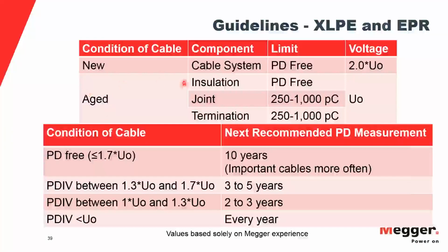You have to consider that the insulation material is constructed completely different. Extruded cables are a single extrusion. They're rubber cables. For a paper lead cable, you have these wraps of paper, upwards of 100 wraps of paper around. It actually takes a little bit of effort for the partial discharge to jump these layers. So it has to jump hundreds of layers, and each one of those takes some effort. So you can have some very high PD values with a cable that's actually pretty reliable.